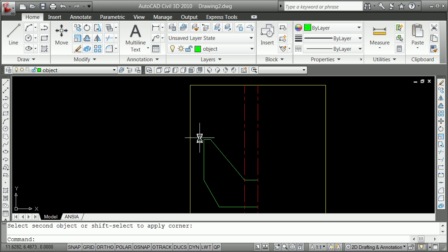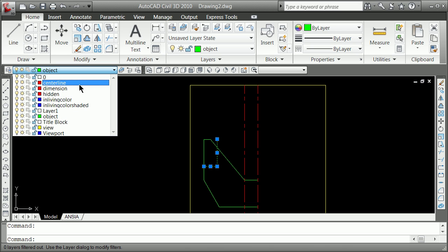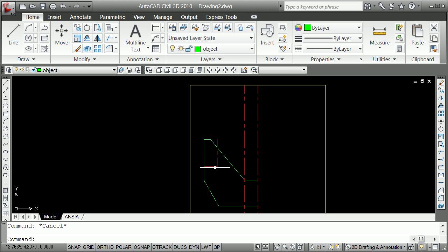So I'm going to go ahead and realize that I can offset 2 down, and I can offset 1 over. And I have now here the establishment of the center of the big circle. Once again, it's not a bad idea to do fillet radius 0. You don't need to do that, but now you establish the 2 points there, and then left click right away, change it to center line. That gives you your circle.